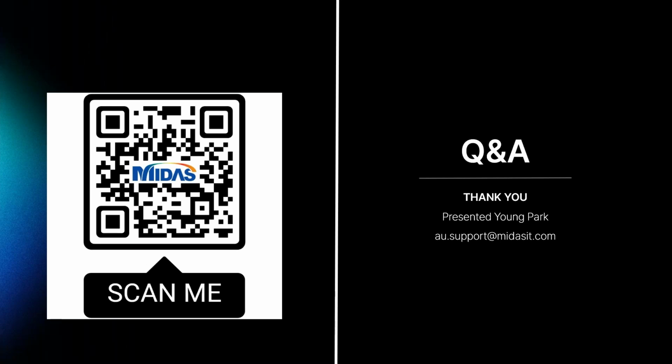Pranav, could you take this? Debonding API, let me just read it again. Previously it was advised to have a node element at the end of the different debonding lengths. Does the API automatically update the node, change the element length? No. So whenever we provide a debonding length, it does not have to modify the elements, because we are not actually changing the length of the tendon, but we are just adding a debonding length up till a certain point. So the elements are nowhere involved in this, just the debonding length can be changed. I hope this answers your question.